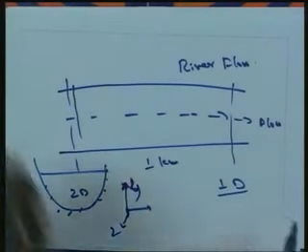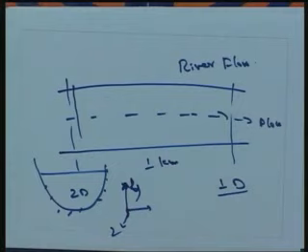Or if you want a complete analysis, we can go for a 3-dimensional analysis. So as far as dynamics of fluid flow is concerned, depending upon the problem we are dealing with, we will be considering 3-dimensional, 2-dimensional or 1-dimensional flow. Whenever we need to approximate or simplify the problem, we will consider the 3D flow as 2D flow or 1D flow.